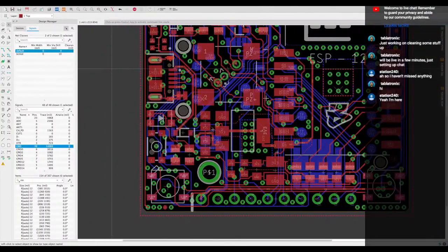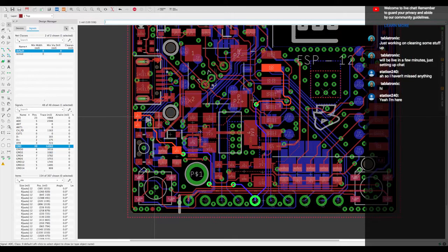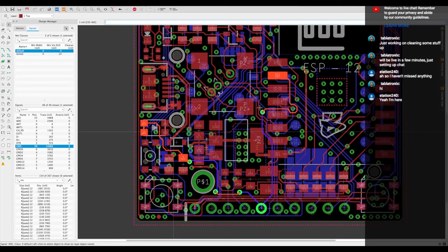Whoops. And another problem is, I don't know if you saw it when I highlighted it, but my ADC line goes 1, 2, 3, 4 vias, 4 layer changes. I mean, when you're doing microvolt measurements or any high speed or low voltage measurement, you probably shouldn't do that.